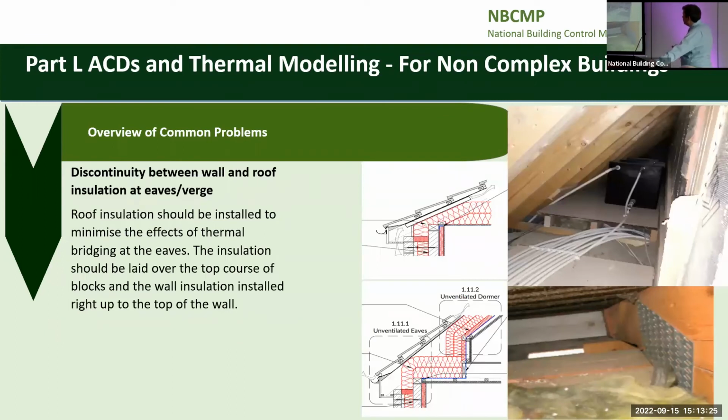Also, with this detail that has now come in, the insulation needs to extend down into the cavity closer. The guy that's doing the attic insulation, he's the last man. He probably doesn't know what he's doing, but who's checking to see that he's filling in that area to make sure it's scraping down there?